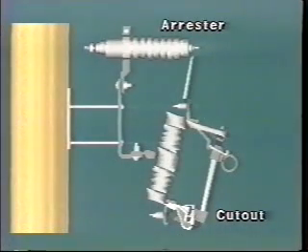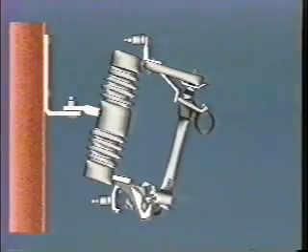The lower end of the jumper is attached to the cutout arrestor combination utilized to protect the distribution equipment from faults or overloads. The cutout arrestor is mounted to the face of the pole with a bracket that gives additional clearance for the cutout arrestor unit. Or, where separate cutouts or arrestors are used, a combination standoff bracket supports both units with a single bracket.